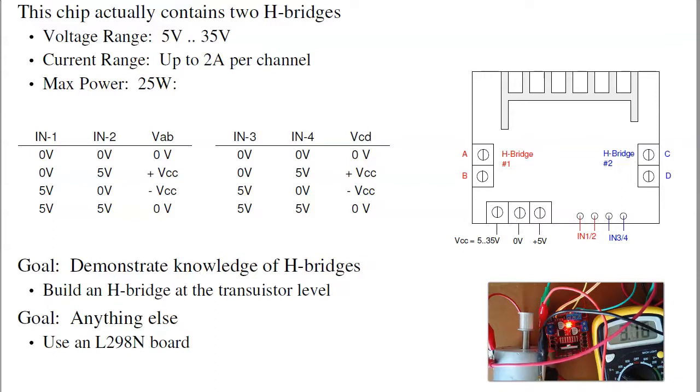So that's kind of an H-bridge, similar to a transistor. A transistor can turn a device on and off. An H-bridge has more options. I can make it go forward, make it go backwards, I can go active braking, or let it coast. And that's lecture number 13, H-bridges, for ECE 320 Electronics 1.